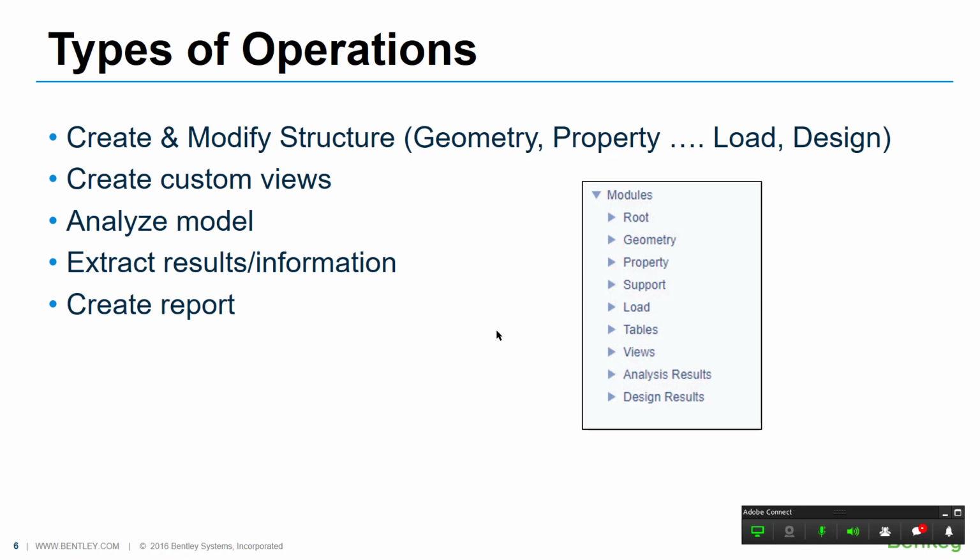For example, you have some in-house program which designs the foundation of your structure. For that you need the support reactions, and what we basically do is copy the support reactions from the post processing mode, select the load cases, and select the supports whose reactions we are going to export. That process can be automated using the OpenSTAAD function. You can just write your code and run it, and the program will automatically extract all the support reaction information to Excel or whatever program you are going to extract the values with.